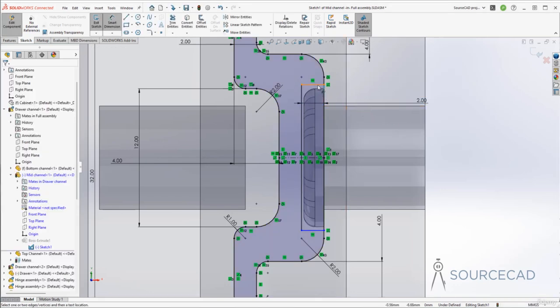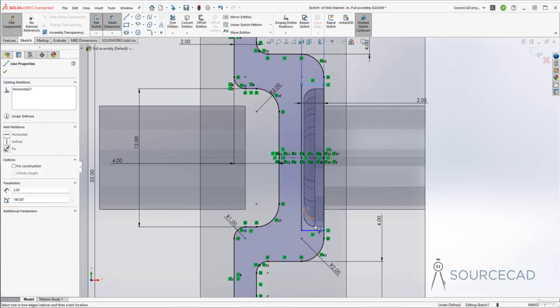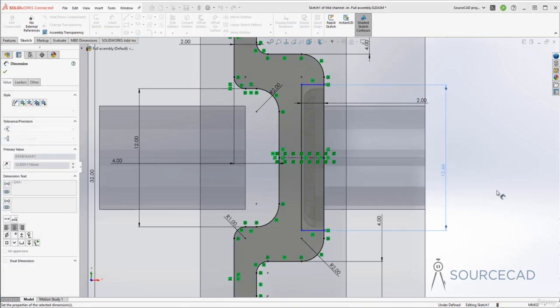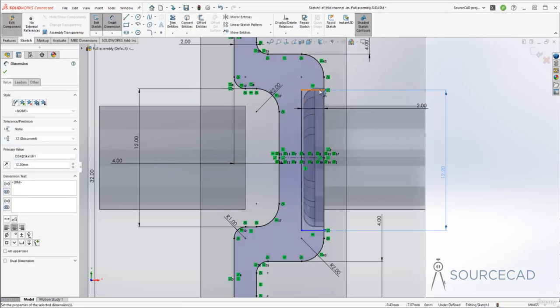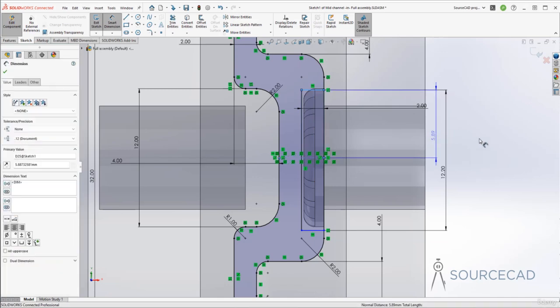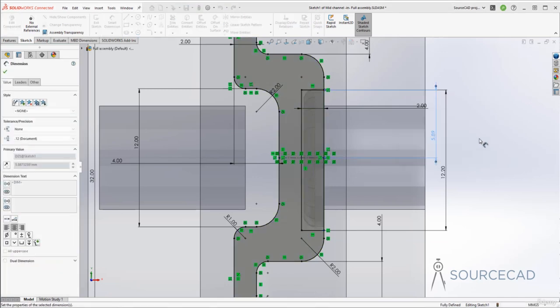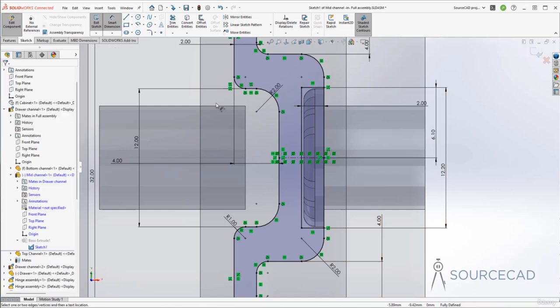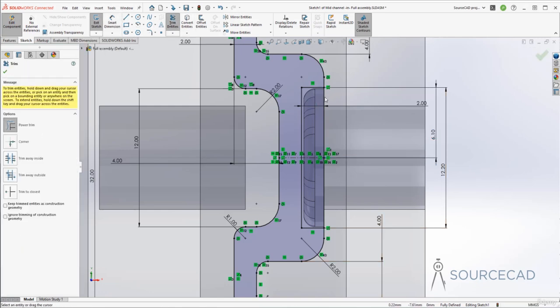And then we have this gap. So this total gap is 12.2 and half of this gap is, well, 6.1, of course. All right, and we have some room here and here as well. So with this groove, we will be able to remove this problem. Now we'll trim it. So go to trim and let's just trim this and this line.